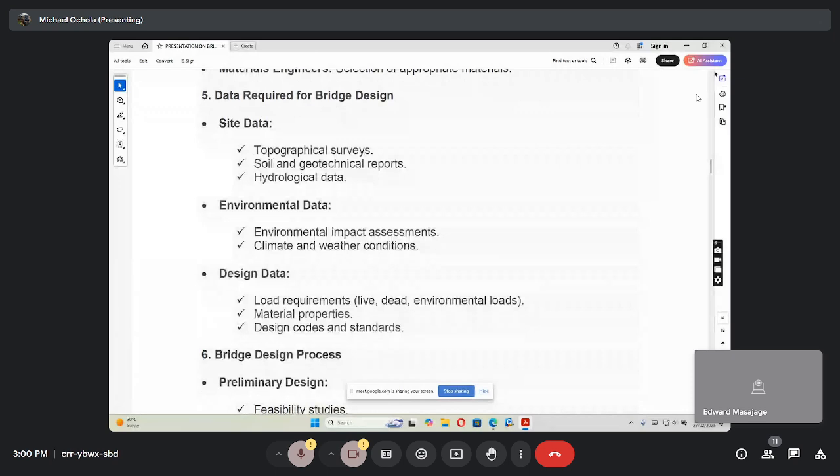So tomorrow when you want to design for fatigue, or you want to do bridge condition assessment or bridge ratings, your bridge is already 40 years in service. It may not be carrying the same load that it was designed for 40 years back because of exposure to environmental load and traffic. You may find that if it was designed for 50-ton trucks, by that time maybe 5 tons is gone, so it can only be working for less. So you need to understand all this dynamic for you to move on.